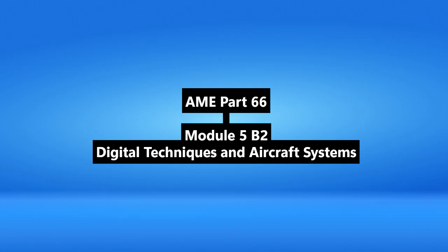They do. And modern digital electronics, with their low voltage levels and fast signals, can be more susceptible to EMI in general. That's why the technician's role is vital. Proper installation, ensuring shielding is intact, like LRU cases being properly closed and grounded, using correct bonding and grounding techniques, it's all part of maintaining the aircraft's overall EMC. Reassembling an LRU incorrectly might compromise its shielding. Attention to detail is key.